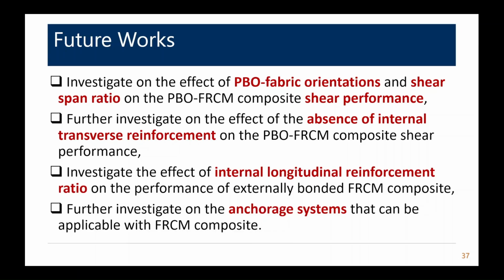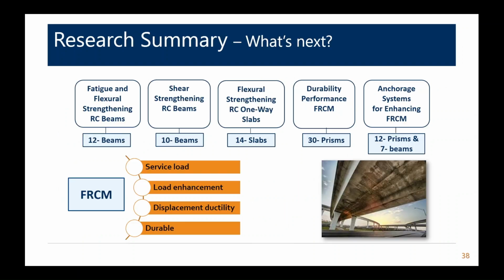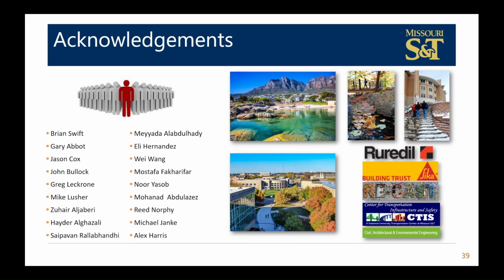So these are just some future things that I think we need to look at more in terms of shear performance. We did some work with and without internal stirrups, transverse reinforcement, and had some interesting observations there. There are other anchoring systems that could be looked at, different reinforcement ratios. I do think we haven't done this in Missouri, but I was hoping to do some type of implementation and monitoring, maybe some load testing, and apply it to some physical structure in terms of a bridge.